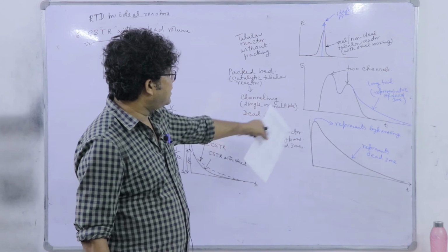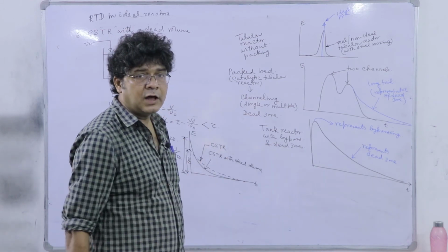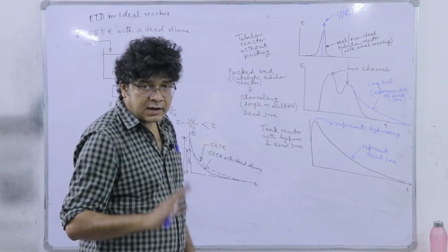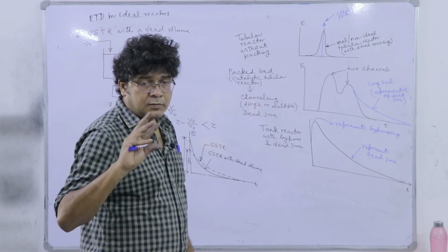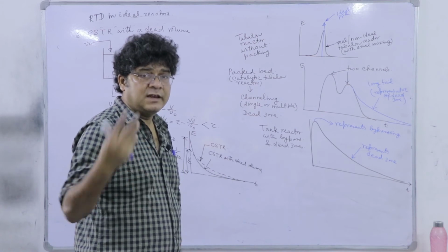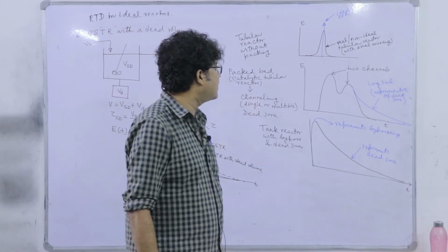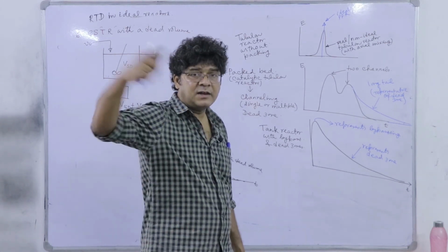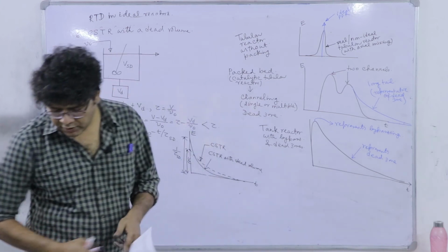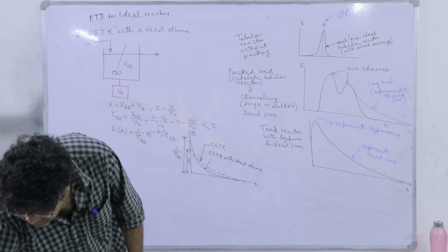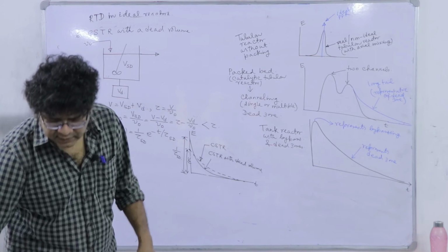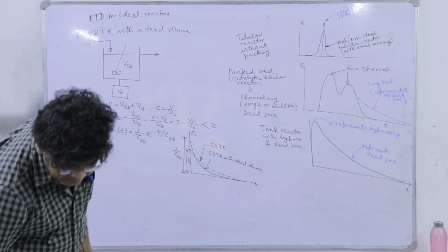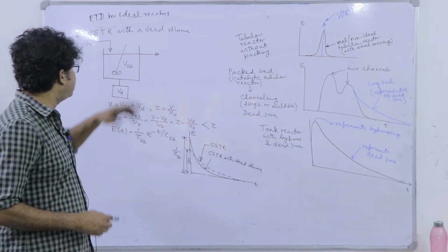So, because of that, we have to go for online RTD analysis, and if I am getting this sort of RTD curve, we know what the identifiers, the signatures of these non-idealities are, like bypass or this long tail, what they actually represent, multiple spikes, etc. Okay. So, before we go for series combinations of ideal reactors, let us have a discussion regarding the CSTR.